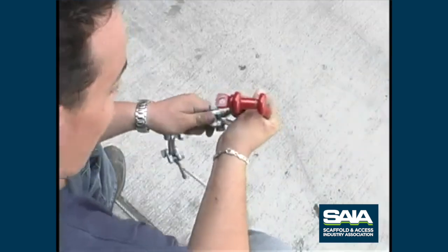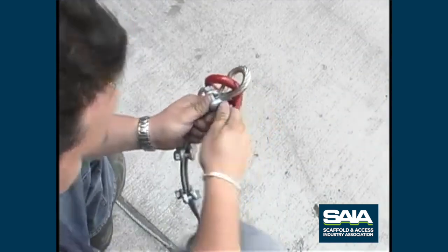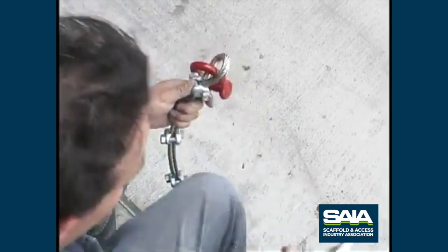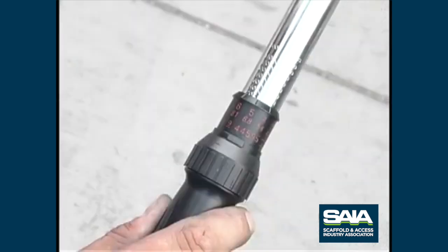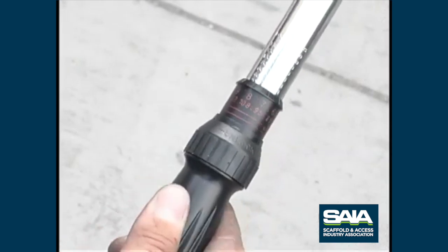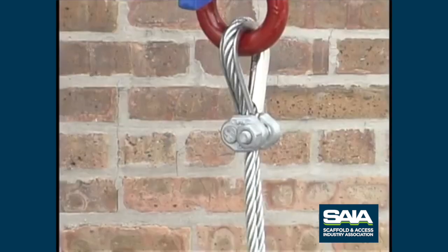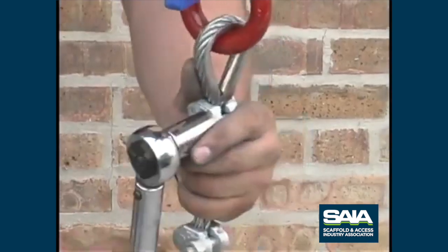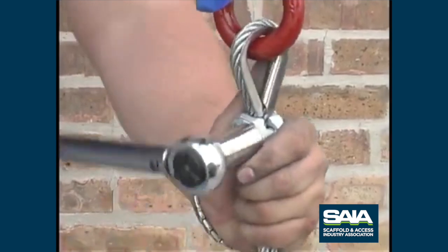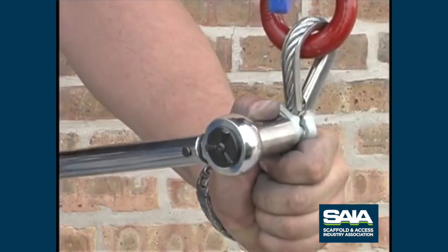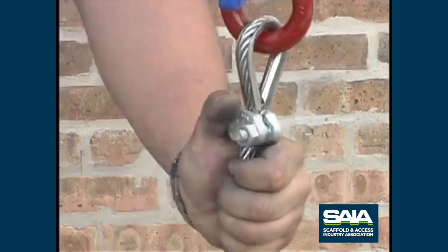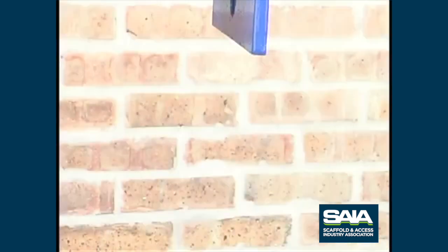For 5/16" wire rope, the first J-clamp should be next to the thimble and the others every 3 inches apart. Follow the clamp manufacturer's torque settings and torque specifications. Retighten the clamps periodically, since wire rope will stretch, causing its diameter to become smaller once load is applied. This could result in the clamp becoming loose.